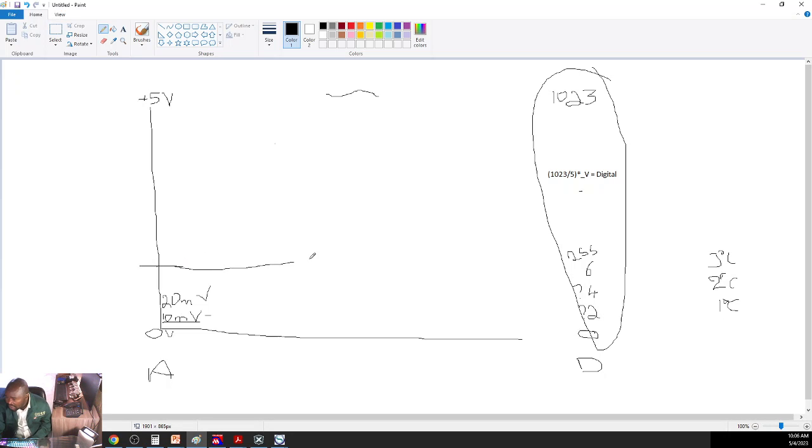If I consider only the lower part, why am I considering the lower part? If the aim was to display temperature for a room temperature, where you have to control a fan and a heater, if you get a result of 255, you divide 255 by 2, you get temperature. The temperature will be 128 degrees, or at least 127 degrees. That means nobody will be alive to monitor that temperature.